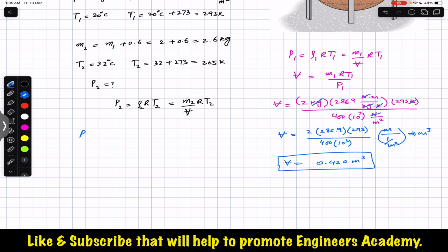So P2 is M2, which is 2.6 kgs, into R, which is 286.9 joule per kg Kelvin. So joule is Newton meter per kg Kelvin into T2, which is 305 Kelvin, and divided by the volume.